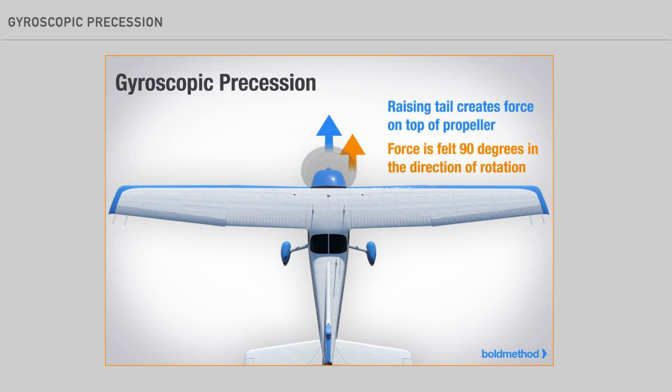During the takeoff roll, gyroscopic precession is most noticeable in tailwheel airplanes and creates a yawing moment with pitch changes. Conversely, yawing about the vertical axis will cause a pitch moment in both tailwheel and tricycle gear airplanes.